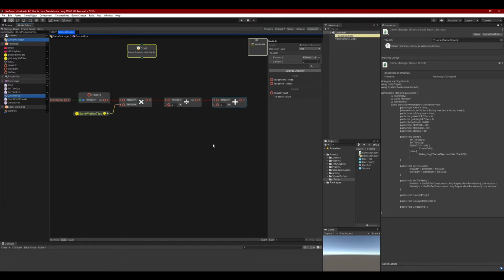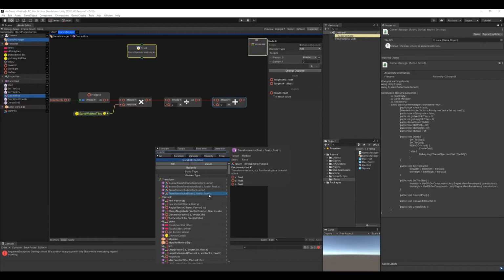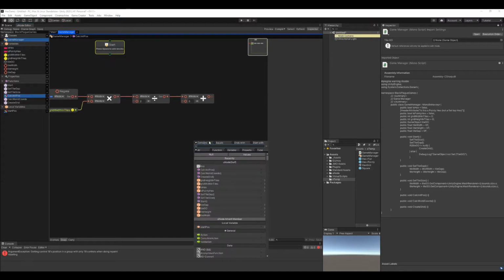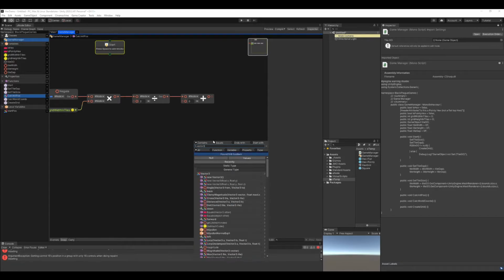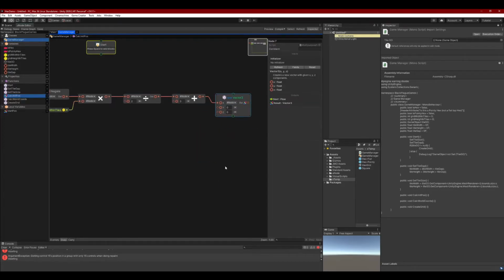And this will be plugged into a new vector 3's x-axis. So we're going to go ahead and grab a new vector 3 that shows all 3 x, y, and z. Let me select the new one. There we go. Oh, that's the new one, but it doesn't have the actual values that we need. So we'll go ahead and do that again. Select the third one down. There. Now we're going to go ahead and pump that into the x-axis.